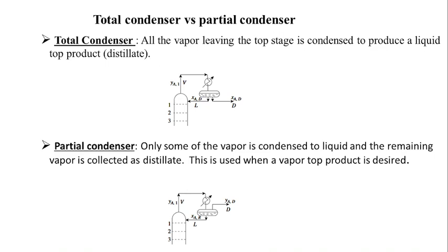Yes, sir. Downcomer width I understand, but weir height. How much should the height be, what is the optimum height, sir? Okay, right. If you want a higher submergence, you have to go for a higher weir height. Now, suppose you are using 4-inch bubble caps.